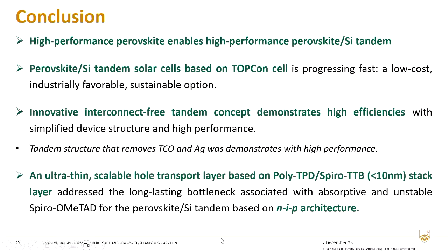When it scales up to 20 square centimeter, the efficiency is just around 29%, so that's around 6% efficiency loss. With the area of 20 square centimeter, that is still at least more than 1 order of magnitude smaller than what is required for commercial products. So we can imagine how much further efficiency loss there could be. Also important, these 29% efficiency cells are made with non-scalable methods. They are still using some non-scalable methods like spin coating in the lab.